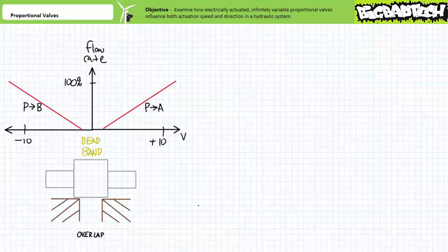A proportional valve is any continuously variable, electrically modulated directional control valve with more than 3% center overlap, whereas a servo valve is any continuously variable, electrically modulated directional control valve with less than 3% center overlap. Given proportional valves are already known to have tight performance standards, this is to suggest that a servo valve is a proportional valve with even tighter performance standards. For this reason, I do not differentiate between proportional valves and servo valves because a Venn diagram of the two would include servo valves as a subset of proportional valves.